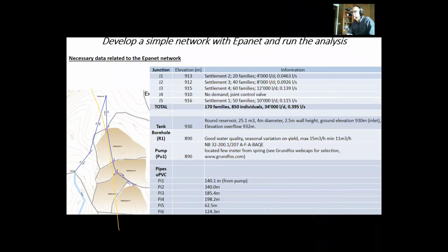The thing is that if you want to pump all the water for one day in a short time, you need a big pump and a big tank. If you want to pump the water over many hours, you might need a smaller pump and a smaller reservoir. This is a fine tuning that we are going to see later when we do time analysis. And then you will have the pipes.